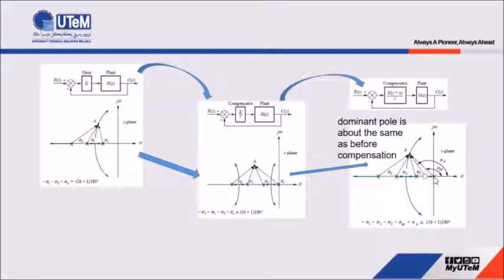That means with a certain value of K, the root locus for the system comes back to the original root locus of the original system without the PI controller. That is how we can improve the performance in terms of steady state without affecting transient performance.